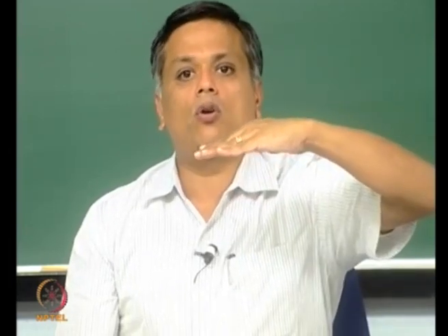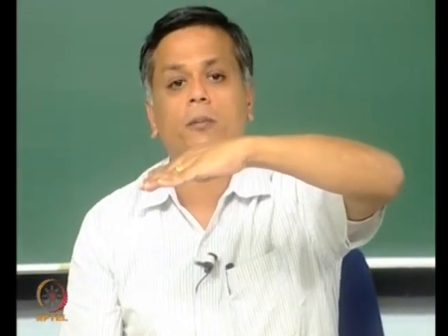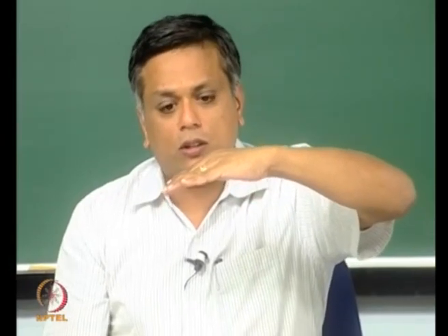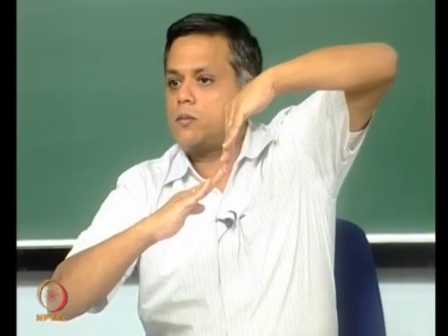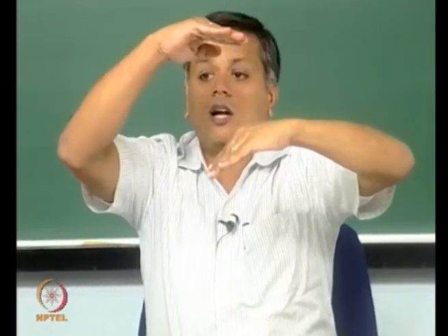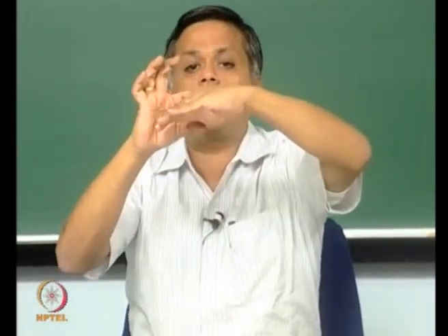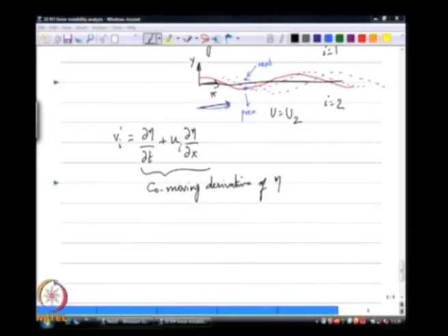One is no growth in the amplitude, just movement of a sloped meniscus, in this case a wavy meniscus, and the second kind is where the meniscus is just growing in time. So, the trough is coming down and the crest is reaching for higher values of y. That in itself means that there is a y direction velocity.